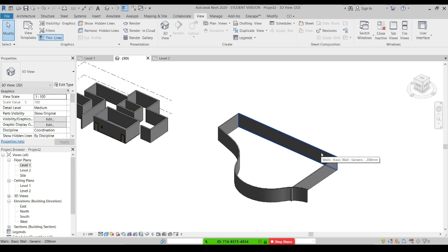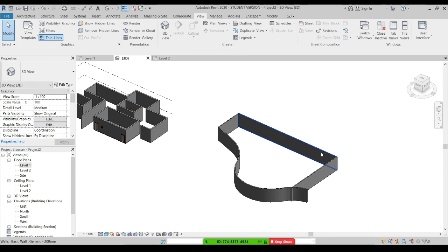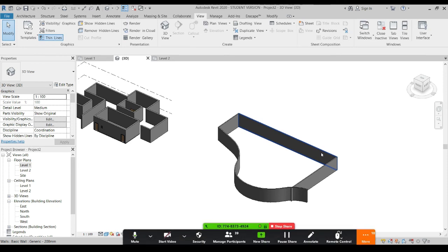Well, level 1 and level 2 is what is set up in the default template by Revit. But usually in our standards or in our office, this is not what we have. We have the walking side level, or the sidewalk level, or the street level, and then we have ground floor, first floor, and so on. So we can create different levels as well.